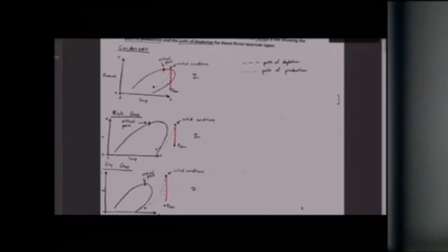Now, if your permeability is high enough, and this is a true story from my professional career, the state of Wyoming, if you show that you have retrograde condensate and you're high enough permeability, they'll make you shut in the reservoir until you instigate a pressure maintenance project. Because the state of Wyoming, you come up and get your test over here, guys, the state of Wyoming doesn't want to lose the revenue on that liquid. They're going to make you operate this reservoir correctly.